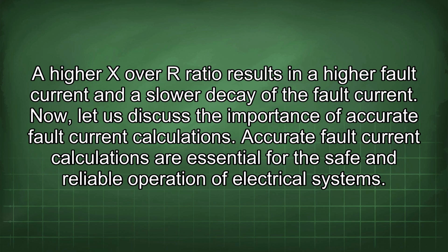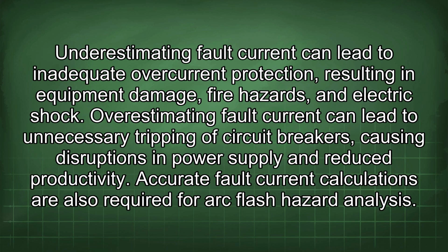Now let us discuss the importance of accurate fault current calculations. Accurate fault current calculations are essential for the safe and reliable operation of electrical systems. Underestimating fault current can lead to inadequate overcurrent protection, resulting in equipment damage, fire hazards, and electric shock. Overestimating fault current can lead to unnecessary tripping of circuit breakers, causing disruptions in power supply and reduced productivity. Accurate fault current calculations are also required for arc flash hazard analysis.